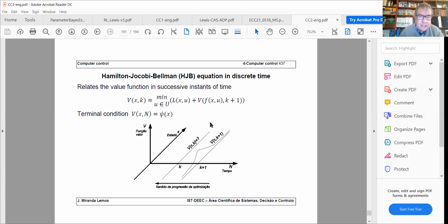Okay, it can be, for instance, a linear combination of quadratic functions that works exactly as we have seen for the linear quadratic problem, because the cost function is a quadratic function. Okay, that's nice. If the dynamics is not linear, then it's just an approximation. Or you can use other types of basis functions, a linear combination of other basis functions, or you can use neural networks.